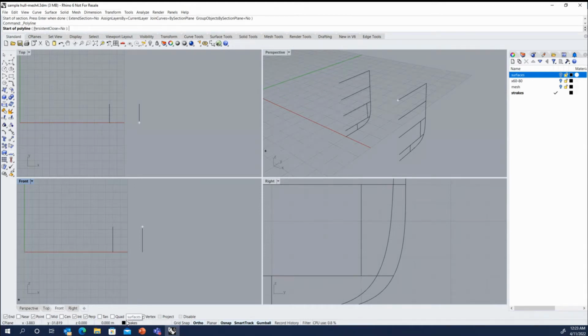If you have multiple types of geometry displayed, your meshes and your surfaces and say some curves, but you're trying to only select vertices from the mesh, then you can very quickly in here just come down, right click, and now it will only snap to a vertex in your mesh, and then come back, right click, and restore all of your regular snap selections.